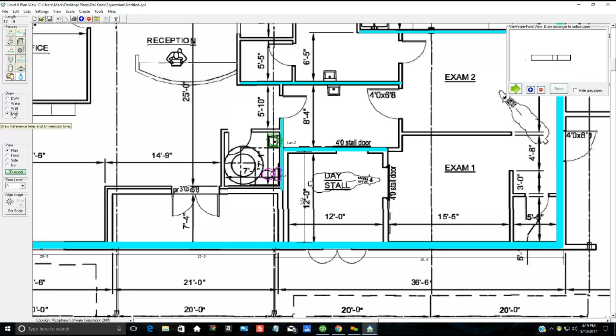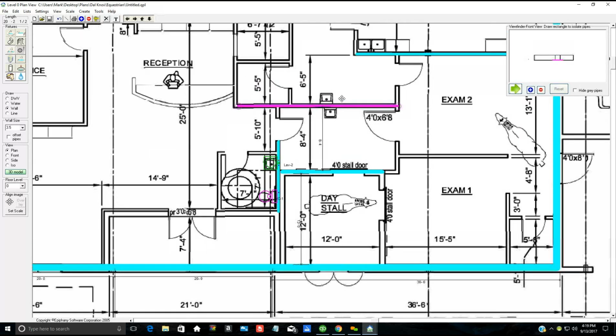We'll click the line tool again, and we're going to do the same with this dimension here. That's 8 foot 4 3/4. I can see that I need to adjust this wall down 3/4 of an inch, and then press enter, and it's pinned in place now. Of course, you can always drag the walls, but they're harder to control when you're looking for a specific dimension.